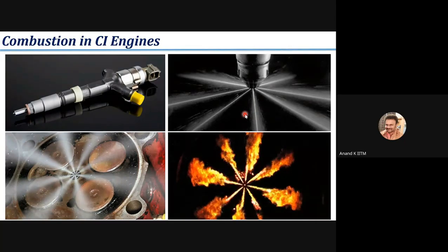So 30 bar, 700 Kelvin are the typical conditions considering a conventional compression ratio, but these conditions are going to vary based on the compression ratio. So you compress air to that pressure level, 30 bar, and temperature also rises due to the compression effect. And you are spraying this high pressure fuel over that. Once you do that, combustion is gas phase, you are introducing liquid phase fuel. So there should be a phase change from liquid phase to gas phase. For phase change, what do you need?